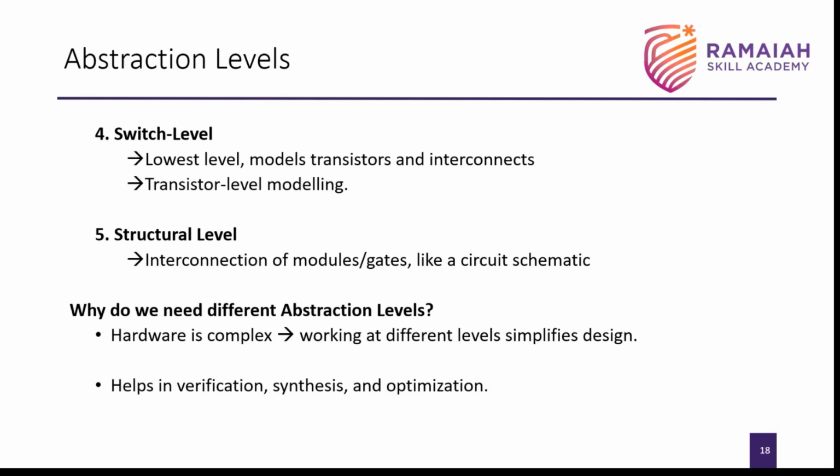Structural level, you have seen the top-down approach and bottom-up approach. You have a full adder, then a ripple carry adder, then an ALU. So my main module is ALU. The submodule is ripple carry adder, and another submodule of ripple carry adder is full adder. So I can design one full adder and replicate that full adder multiple times in my top module. Okay, so this will simplify the way we write the code and also the complexity of the circuit. So this is done in structural level.